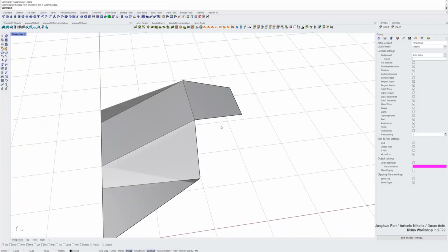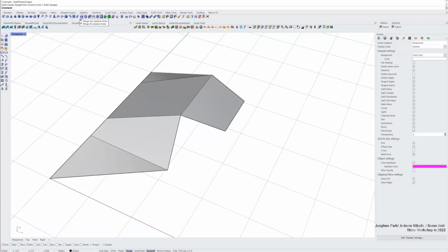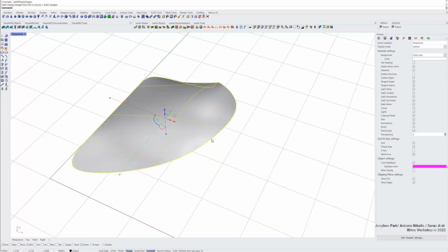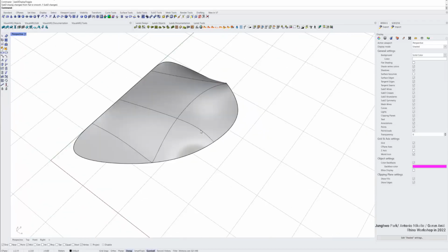Alright? So this append is like you can keep adding the face. It's really good to actually select. And I can click vertex as a snapping option, and then I can add more faces here, for instance, and hit Enter to finish. Then I have another face added in this sub-D object. Okay.